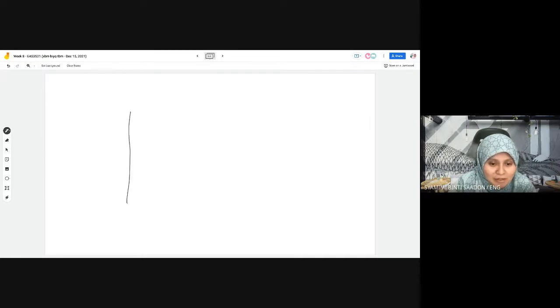TS diagram that I mentioned. Okay, I usually use the TS diagram. We can also use PV diagram, HS, etc. But TS is the most convenient for a gas to sketch, to locate, to represent the gas turbine cycle. Even though this parameter S, entropy, we haven't learned yet, it's okay, we're just going to sketch it. We are not going to calculate it yet.